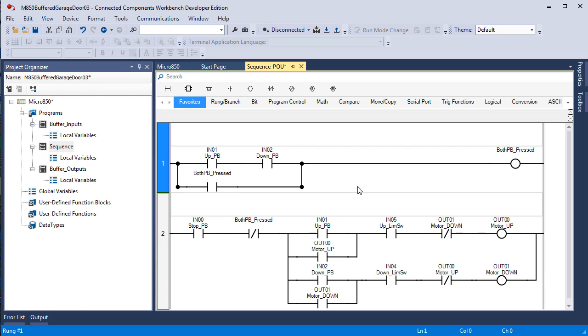I think in the manual I had you download this and try it, so you could see that logically this is moving in the right direction, but it really didn't work, because how in the world would you reset this logic other than putting it in the program mode and back to run, or turning power off and then back on and back into the run mode? It wouldn't reset. So we need something in here to break the logical continuity of this seal-in.